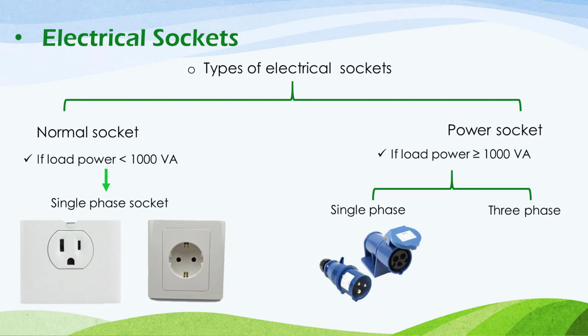And here this is the shape of the single phase power circuit. It has three terminals also, one for the line, one for the neutral, and a third one is the earthing wire. And you can see the earthing terminal is larger than the line terminal in its cross-sectional area. And this is to have a lower resistance by having the larger cross-sectional area. So when the resistance of the earthing wire is lower, this helps in absorbing any leakage current, so the earthing system will be working well.